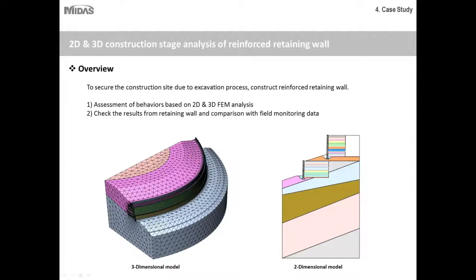So they had to consider the stresses occurring in the wall members along this arc line. They had no option but to have a 3D analysis model. Had this been a relatively straighter wall, then 2D analysis would have been sufficient, and this enabled them to obtain the relative displacement of the soil strata along the periphery of the wall.